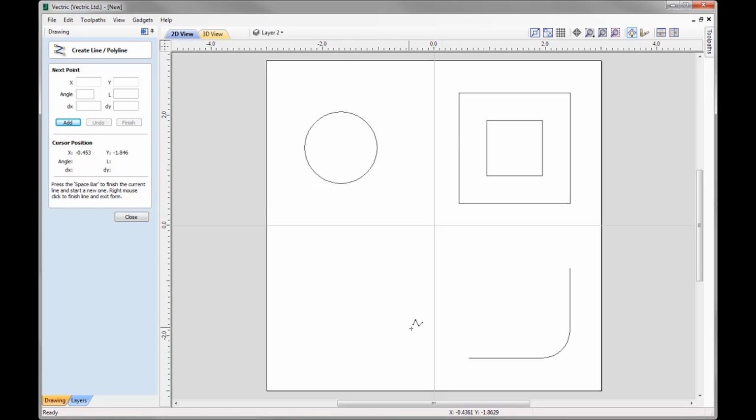So let's have a look at the shape in the lower right hand corner. I'm just going to run my cursor over that to wake it up. Then I'm going to move the cursor away and randomly move that around, and you'll see now that we're displayed with a blue line running vertically through the centre of the object. When you see a blue line, that's the software's way of telling you you've found an object bound. In this case, we've found the centre vertical line for the object that we've woken up.